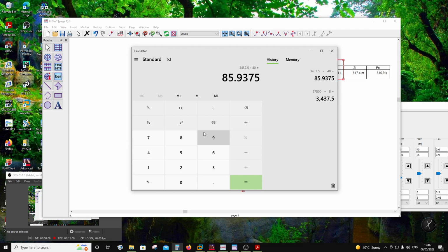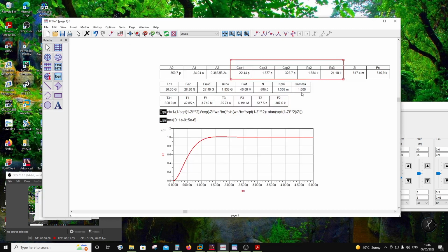If I go to the 7-bit, I would have to increase the K phi a lot. So almost like, I have to go up to 2 milliamps from the charge pump, right? So 2 milliamps of source and sink. That means that I have to work with very large transistors to have the right swing, where the impedance of these charge pump current mirrors is large for a large swing, right? So twice the overdrive is what you will have: 2 VDD minus twice the overdrive.